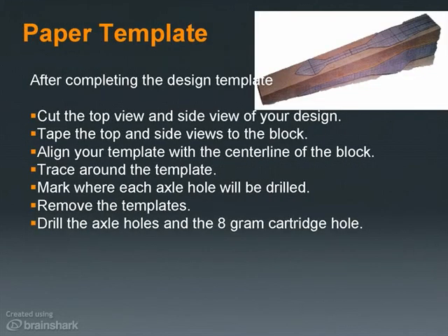Cut your paper template and tape the top and side views to the block. Align your template with the center hole of the block. Trace it out. Make sure you mark where the axle holes will be drilled. It's time to remove the template and drill the holes.